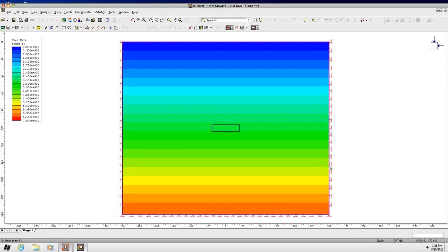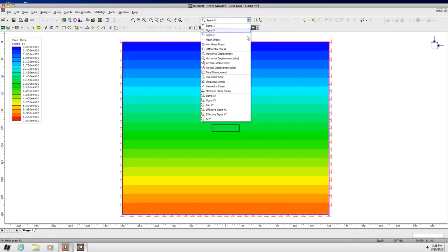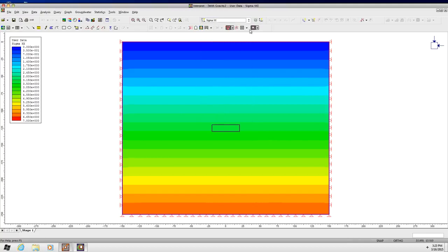So I have the boundary conditions just the way I wanted, and the vertical stresses, sigma y, y, are the exact gradient that I want, 0 to about 6.7 MPa, and all you have to do is multiply the unit weight by the depth and check it. Sometimes I'll spot check it, but you can see that it's pretty clearly got the kind of uniform gradient that I'm looking for. And I also check all the other stresses to make sure they're the same. Sigma x and sigma z.